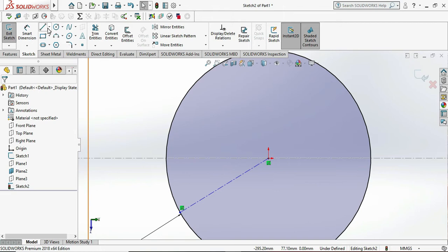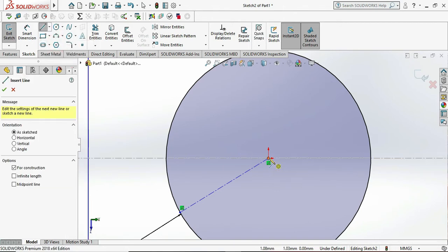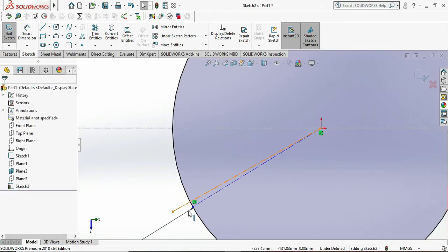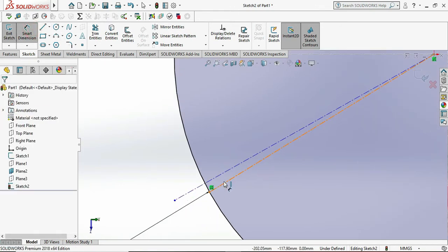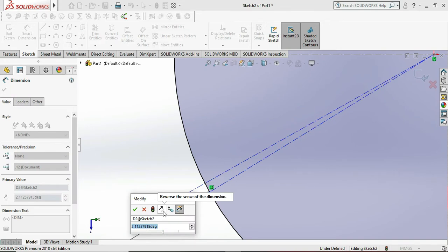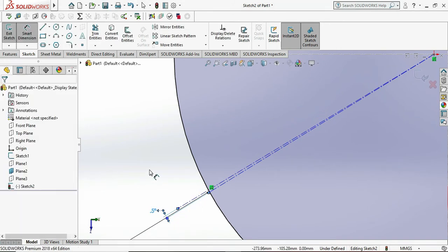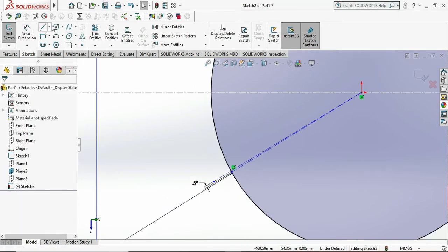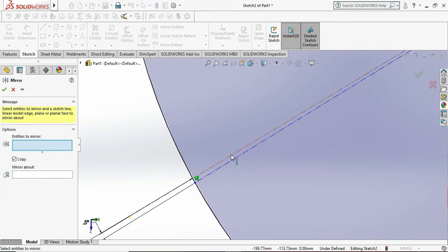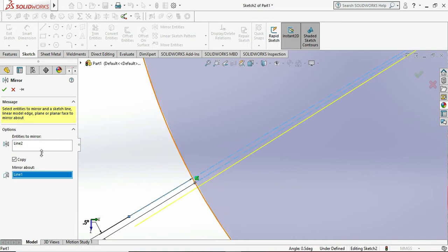So take the reference line like this, which helps us to convert this duct into the sheet metal form, which is very essential. Otherwise your duct will not take a sheet metal form or will not flatten. This is the sheet metal rule. If your object flattens, then it is correct in sheet metal. Otherwise it is wrong.